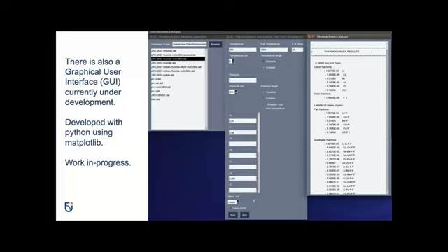JRC database where the user can span a series of temperatures. So in this case here, start at a temperature of 300, move to 1,000 degrees, have 10 steps going across it, specify the temperature, specify the pressure and the pressure unit, and then the user can also specify how much of each of the components is included in the calculation.